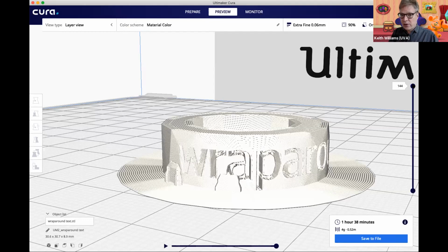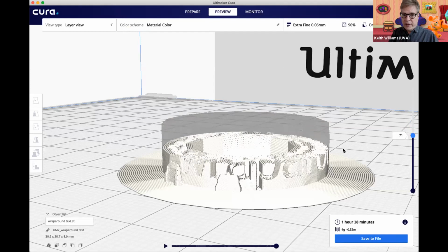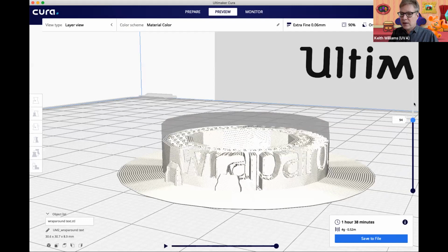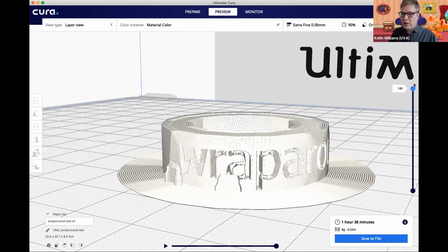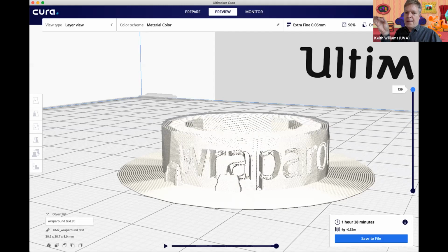And as we look through, remember what limits the resolution along this direction? What limits the resolution is the layer height here. Now we don't have nearly as many layers. We have 140, 145, 144 layers this way. So the resolution is not super duper. You can tackle that issue simply by using bolder text.